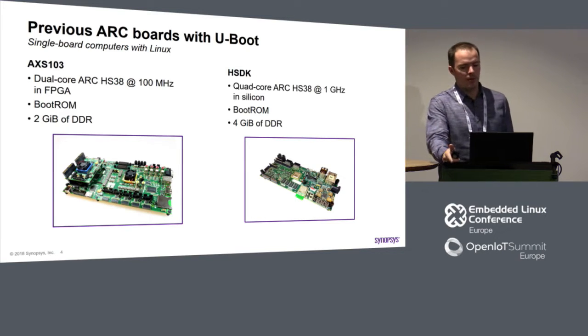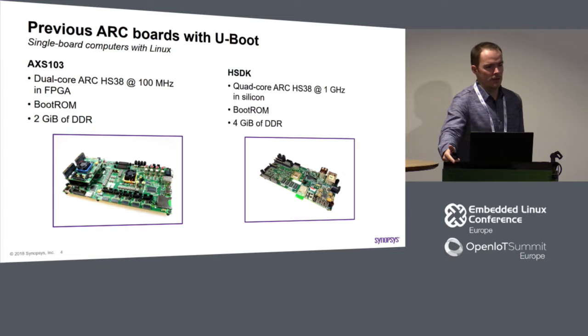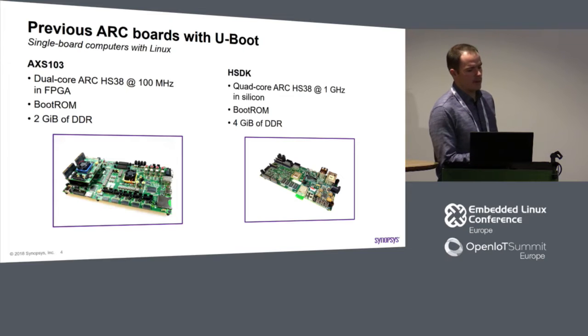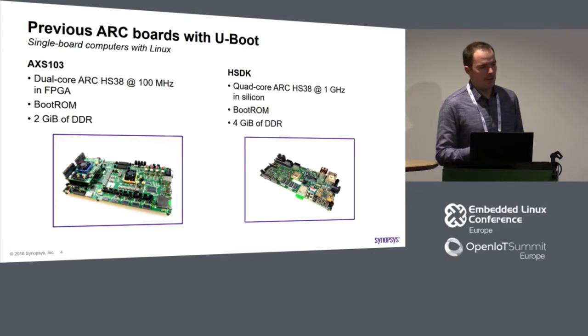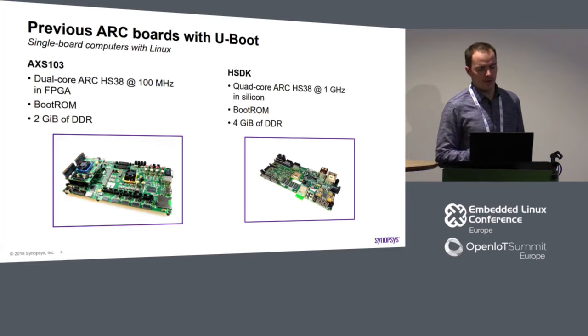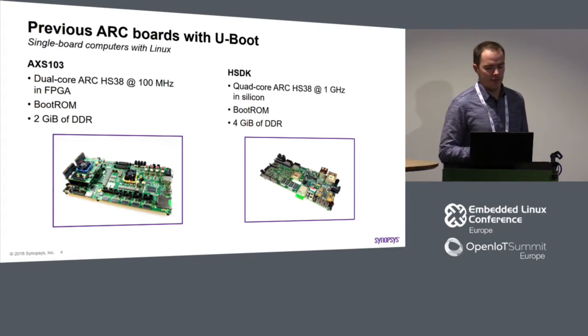U-Boot is basically a bootloader, and its main reason to exist is to load some real payload and start it on the board. Typically it would be some kind of OS. It might be an RTOS, or what at least here we may think of, it will be Linux kernel plus rootfs and all that.